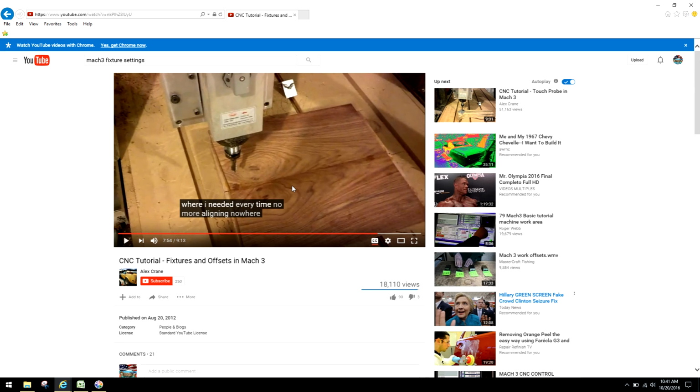If you really want to get crazy, you could use virtually any material you want, from super flat glass. You could use two small pieces of glass that you can get at a thrift store. A lot of places have scrap glass, super flat. You can go to aluminum, whatever you want. The big thing here is precision. You want to be able to switch out a piece of raw material, pop in the new piece, make sure you're locating it in the exact same position with the minimal amount of tolerance available, and then just hit that fixture. You're going to work right away. Just bolt it down and tighten it down, and you're ready to go.